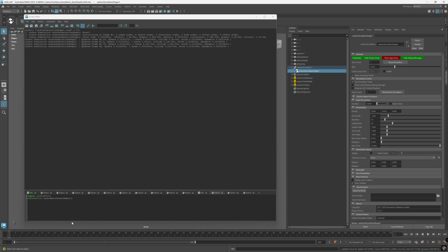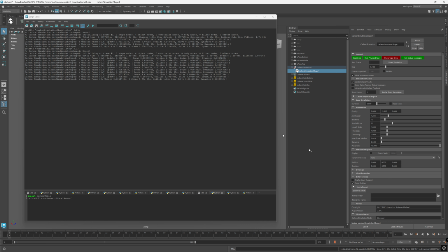And usually you want this feature when you actually have a timeline with substep as well. So your setting in Maya could be a substep setting. If I change this to 0.1, we would simulate, obviously, 10 frames per time step. Go back to frame 1, reset simulation, go forward, and here we are. We have 1.1, 1.2, and so on, all the way up to 3. So we have 10 simulation steps happening.